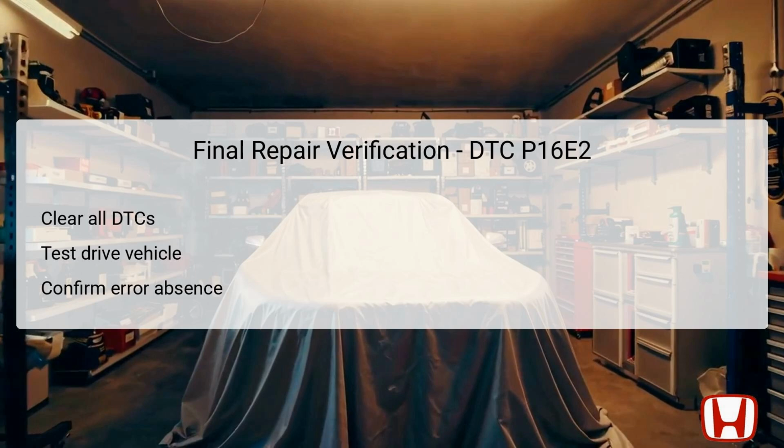Upon completing the troubleshooting steps for DTC P16E2, it's crucial to verify that all repairs have effectively resolved the issue. Start by clearing all DTCs using the HDS, ensuring that any error codes regarding the PGM-FI or the LIN communication error are removed. After clearing, take the vehicle for a test drive to evaluate its operational performance under various conditions.